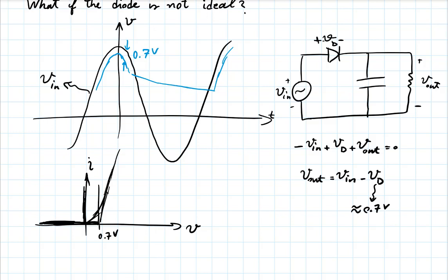Now, is this a problem? Well, depends. So not only are you losing a little bit of the input voltage, but there's also some additional distortion introduced to it. So the output is not a simple cosine minus a constant during that time. It's a cosine minus some value that's itself varying. And so you have some distortion there, but that's fine. This is life. And we are dealing with nonlinear elements, and in general, as soon as you change things a little bit in an electronic circuit, you start having distortion. That's fine. The question is how much you can tolerate.